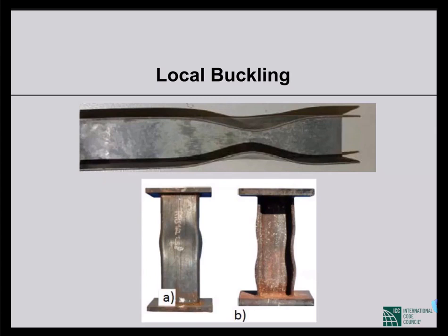Remember, in steel design, the most important thing is buckling. We have to always be very concerned about this phenomenon, which is called buckling. So in steel design, we always have to think about buckling. What is buckling? You know that steel is a very strong material compared to other materials like concrete or aluminum. That's why we need very thin sections of steel to carry loads.